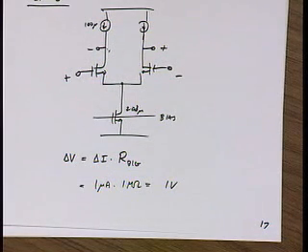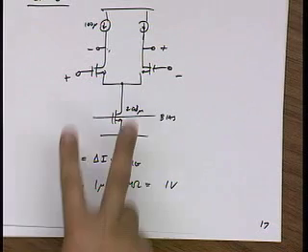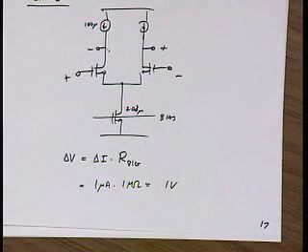So what's the problem if the common mode range is unknown within 100 millivolts? Do you care? Do you have to set a bias on the next stage? I'm AC coupled to the next stage. I don't care, right? And my next stage is also differential, so it's rejecting the common mode anyway. So what's the problem?